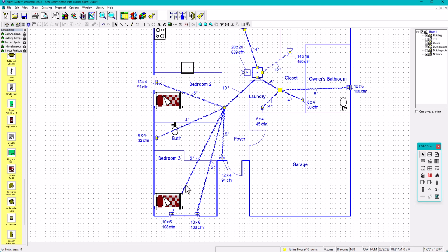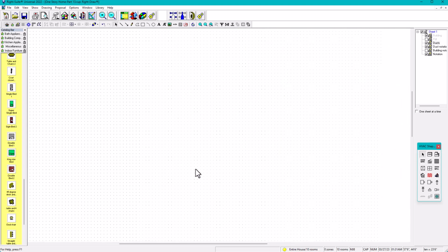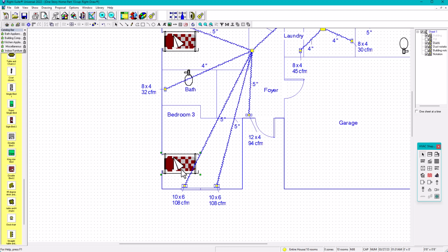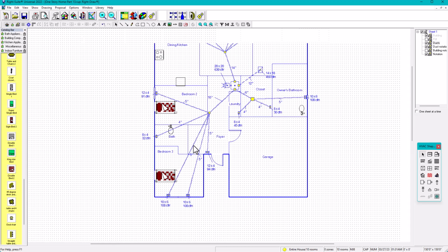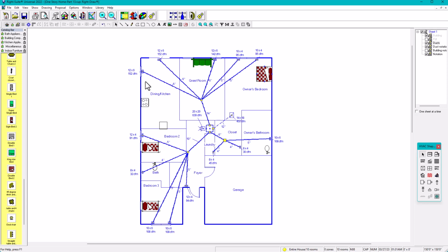So what happens is that this is the latest item we added. So what I'm gonna do is delete this duct. Again, I'm going to lock my building, so that way I don't have an issue selecting my duct. I'm going to delete it, create a new duct, and connect it again to the register. So that's the latest operation I did, therefore it is above this image. So that's the trick. Alrighty, so now we have everything, but you can always go more and more in detail,